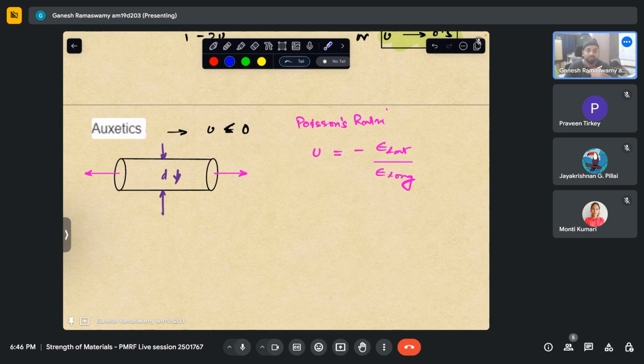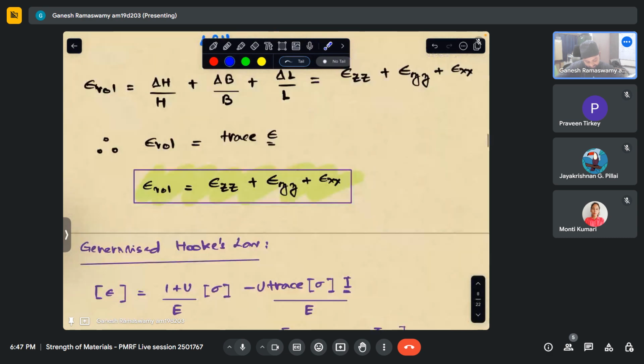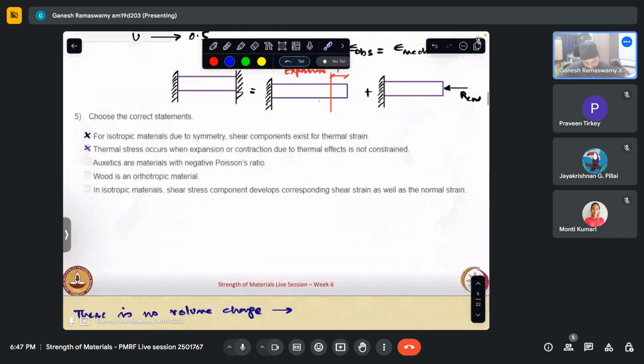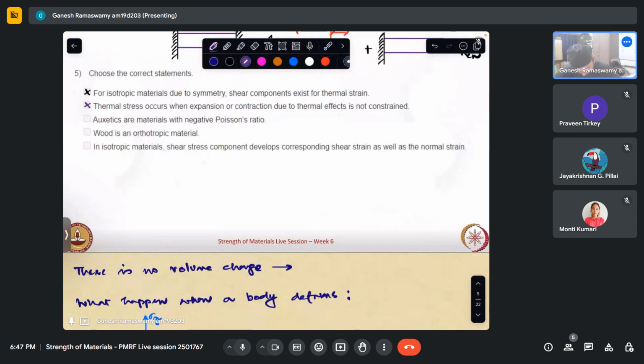So we want to widen the artery where the clog is. So if we were to employ such a cylinder over there, a vessel over there, and if we were to pull it, and it automatically expands its diameter, that will serve the purpose. There are many interesting applications like this for such materials. So these are called auxetics. So auxetics are materials with negative Poisson's ratio.